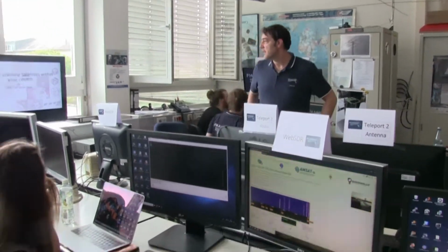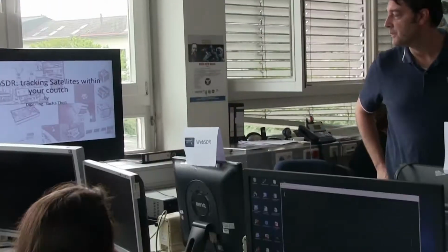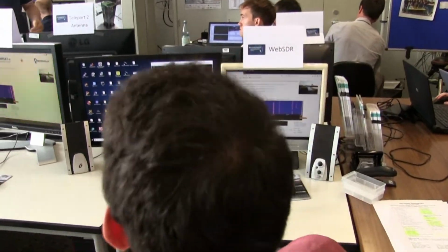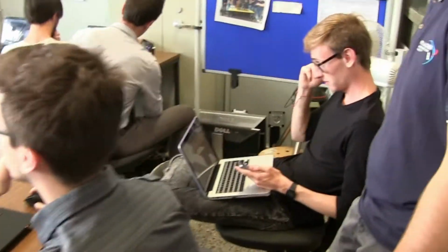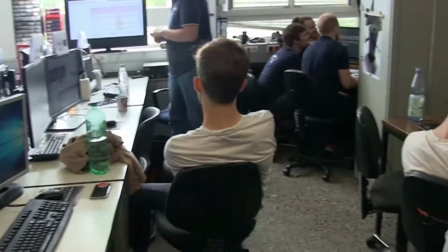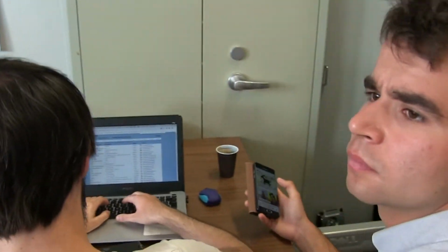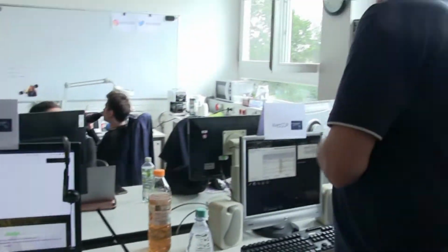Usually, when you work as a flight controller, you never experience what effort it took to carry the signal into that quiet flight control room. In this workshop, the students learn the required steps needed to receive a signal coming from a spacecraft, and what steps are to be done to pre-process the raw signals in real time until the final product, the image, the telemetry data, or just simply the satellite's beacon can be displayed on the screen.